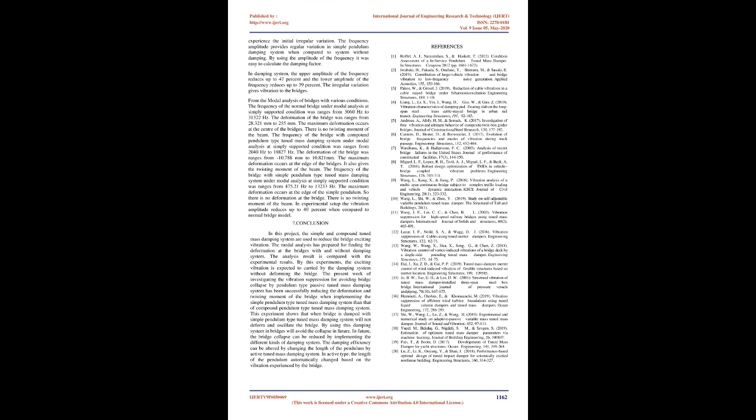The frequency of the bridge with simple pendulum type tuned mass damping system under modal analysis at simply supported condition ranges from 475.21 Hz to 13,233 Hz. The maximum deformation occurs at the edge of the simple pendulum. So there is no deformation at the bridge. There is no twisting moment of the beam. In the experimental setup, the vibration amplitude reduces up to 40% when compared to the normal bridge model.